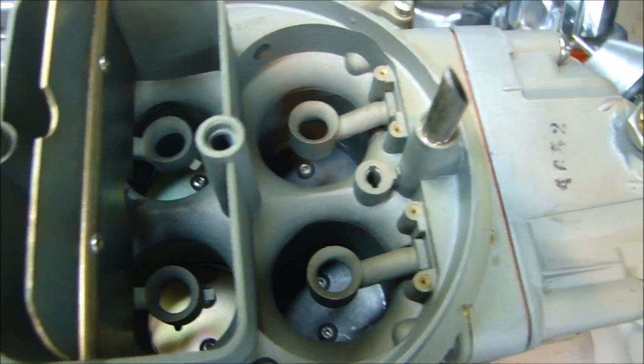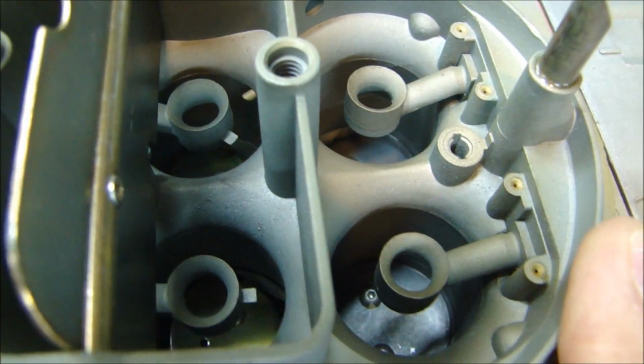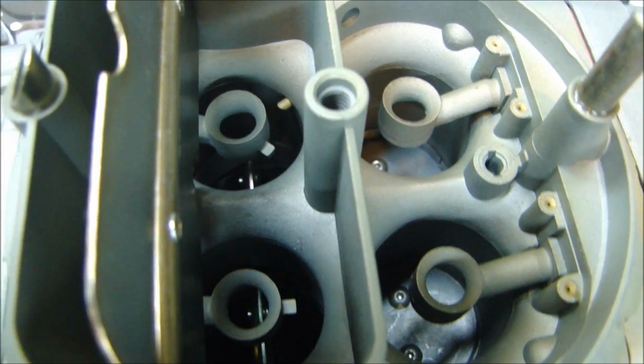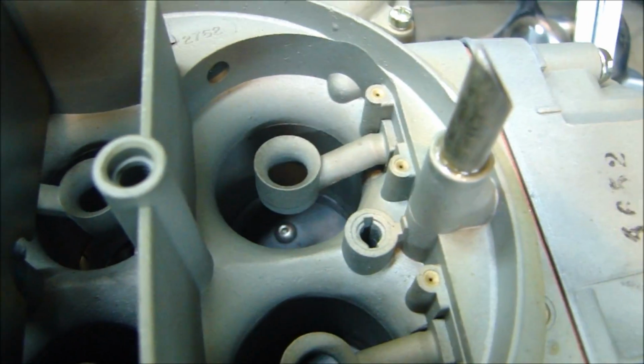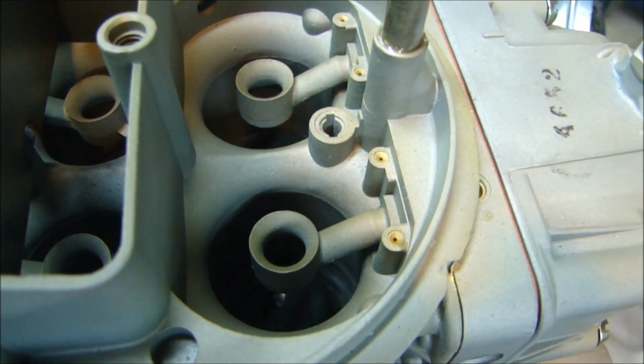And when I talked about fuel metering, now I'm going to open this up. You can see the butterfly down there, I'm going to open it to wide open throttle. See, I'm opening wide open throttle, and when it's wide open throttle, the vacuum secondary would kick in and open up the secondary. So the secondaries in the back are what would open up. See the secondary in the back opening up there.